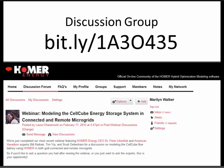So because of that, the way you can model an AC battery is go ahead and put it on the DC bus, but make the inverter irrelevant. Make it bigger than it could possibly need, no cost, 100% efficient. It will have no effect on the modeling. And as far as your results are concerned, the results will be the same as if it was put on the AC bus. The one downside to that some people have noticed is, well, your PV needs an inverter as well. And I should have mentioned this in the beginning.